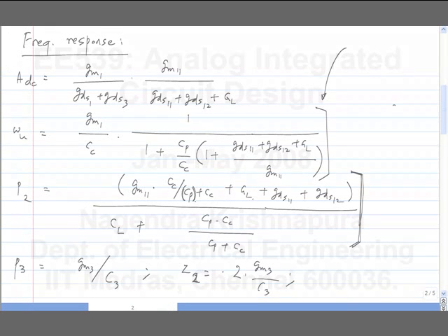So the conductance in the numerator will go on changing, but the denominator changes a little bit. In fact, this will go on decreasing and the load will dominate, so P2 will also keep on moving to lower frequencies. This means that at some point you will not be able to compensate the op-amp. That's when you stop. Obviously, your goal is to minimize the current consumption.